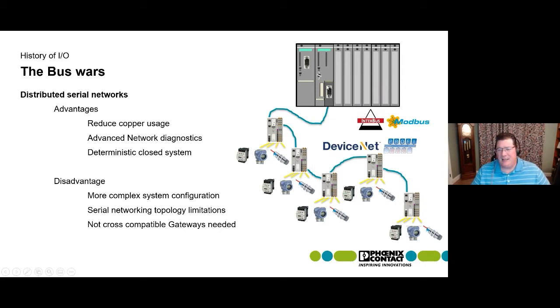So basically, the controller goes, give me your data from station 1. This is broadcast across the entire network. Whoever is station 1 is going to just sit and listen and go, oop, I'm station 1. I'm going to respond with my data. Then it's going to go, I want data from station 2, data from station 3, station 4, station 5, and a sequence is generated. This sequence of commands for pulling data between I/O devices allowed them to create a network that was deterministic.